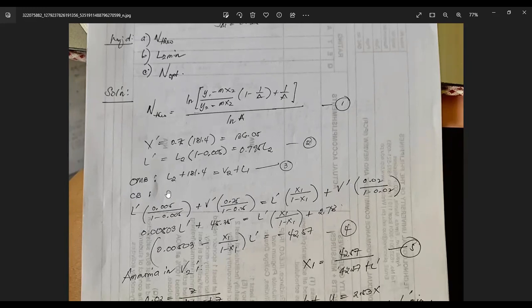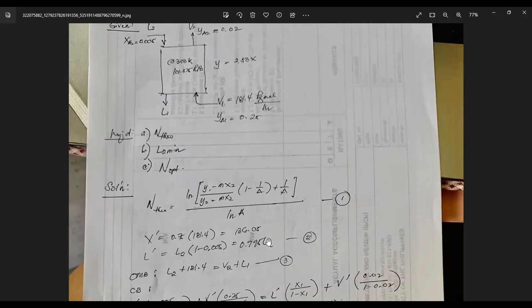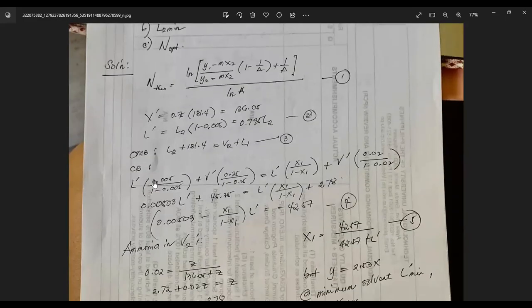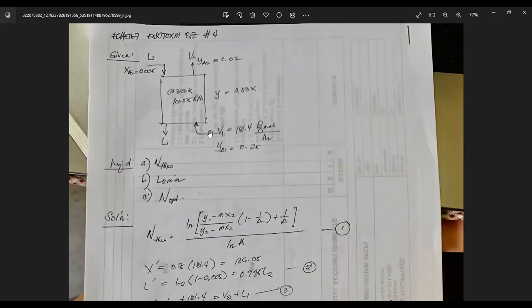You're multiplying it with the mole ratios, not the mole fraction of ammonia on the stream that you're referring to. So in the case of this stream here, your solvent, this is your ammonia over water. So it's mole ratio. Now in your V prime, this is the stream entering.